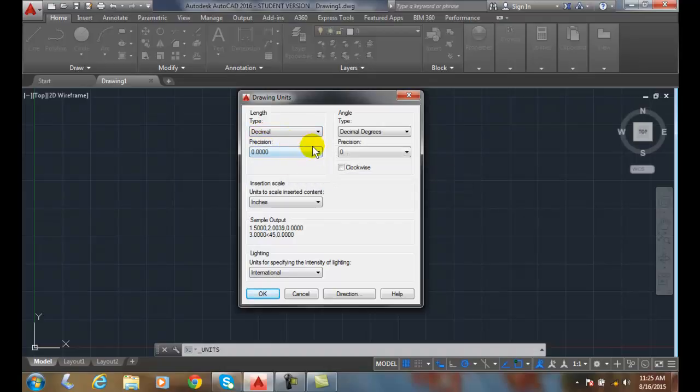Our precision is how much do we round it off? How precise is our measurement? If it's decimal and we're to 4/1000ths, this part's going on the space shuttle. It's being machined to 10,000ths of an inch. Typically an average machine shop goes to three decimal places or 1,000ths of an inch. So we're going to make a decision on how accurate it is.